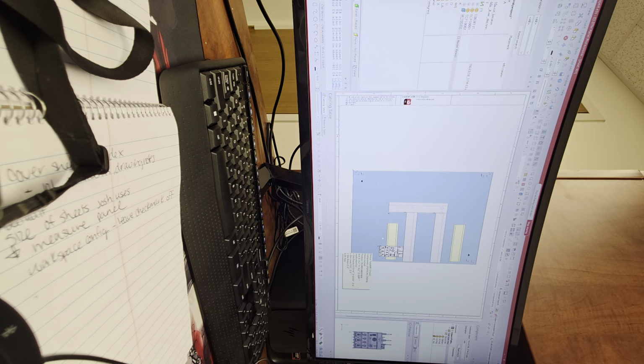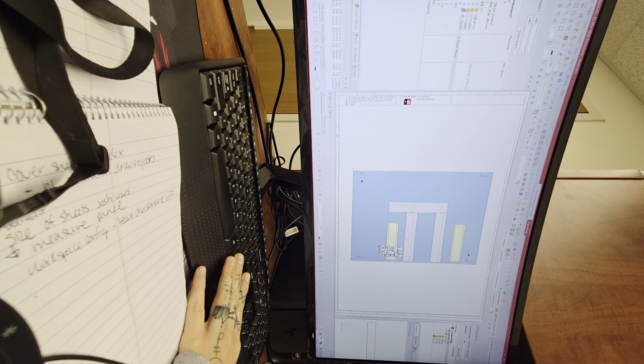But again, for your design, I would delete the duct right above it. So I would delete that one. Actually, don't delete it from here. Undo this once. Actually, I guess it hasn't been deleted yet. Always jump from the model to your device tree structure, because you always want to delete it from the project. So Control left click, Control left click till you see the highlighted item in your device tree structure on the left. And I'm doing the duct? Yes. Control left click. I think it's frozen.